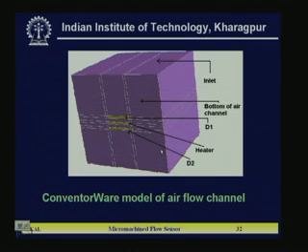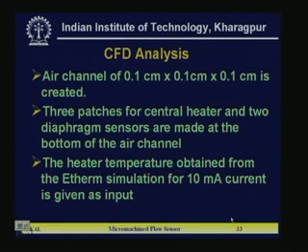It does not look like physically how you are getting it and how you are fixing it in the measurement setup; rather, you have to define some hypothetical structure in the simulator, so that it can simulate using the boundary layer technique, and again it will do some kind of finite element or finite difference analysis to get the flow pattern. Now, for the CFD analysis, the assumed channel is a 0.1 centimeter by 0.1 centimeter by 0.10 centimeter cubic structure, which is created, as you have seen.